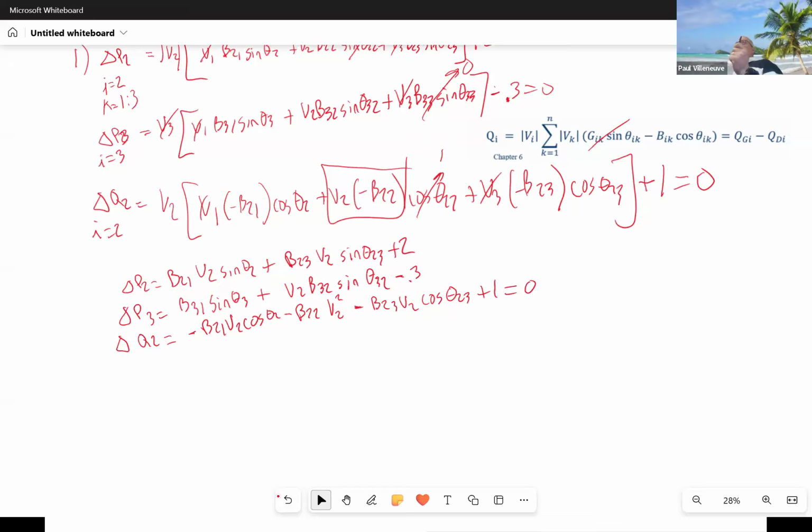When you're simplifying your equations, look and see in my power balance equation, do I have any of those known state variables in there? If you look at the homework, one of the voltages is 1.04. You can still substitute in the voltage 1.04 to get your answer, so you don't need to include those. That's a nice way sometimes of checking your work and simplifying it down.